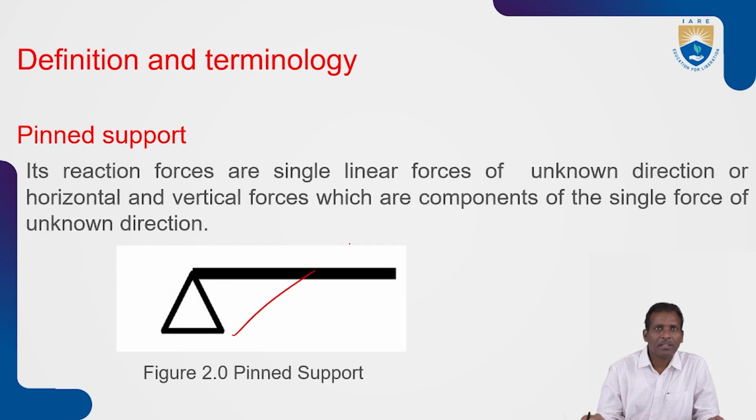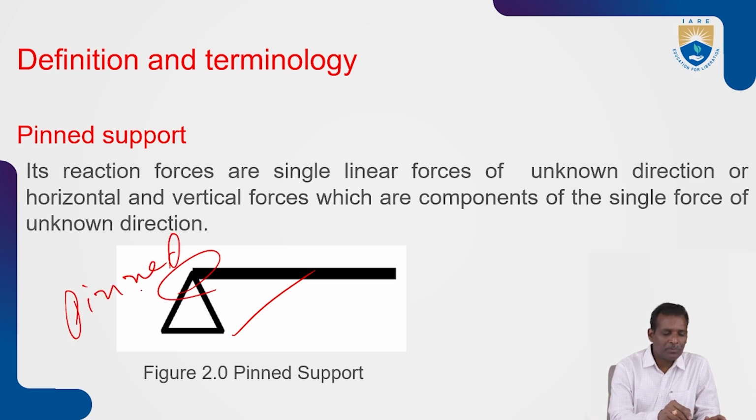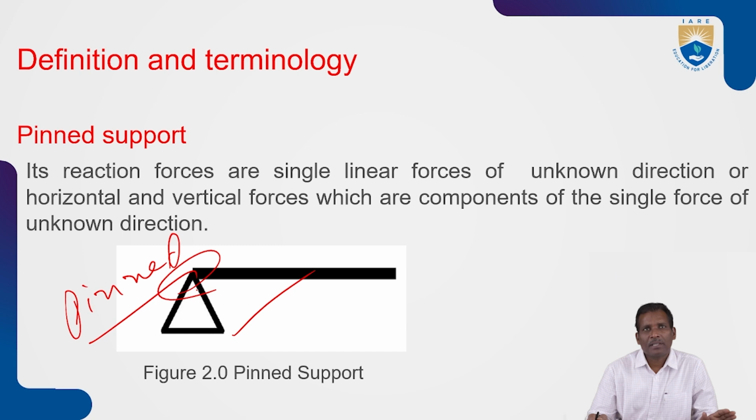See in this diagram, at this edge the end point is pinned. So its reaction is a single linear force of unknown direction, and the horizontal and vertical forces are components of the single force of unknown direction.